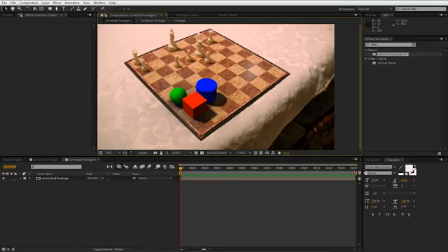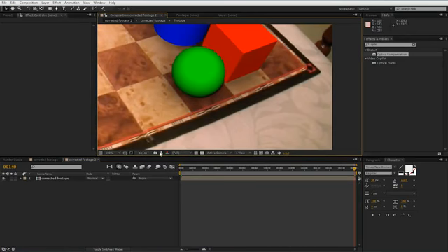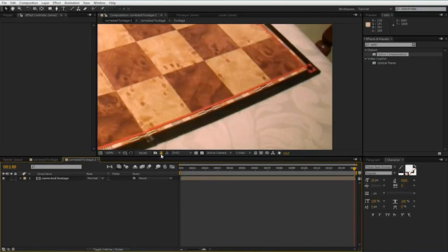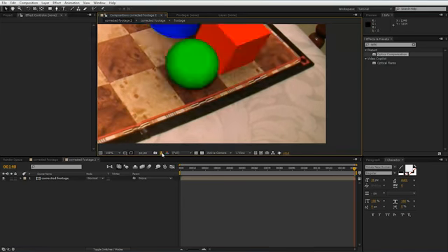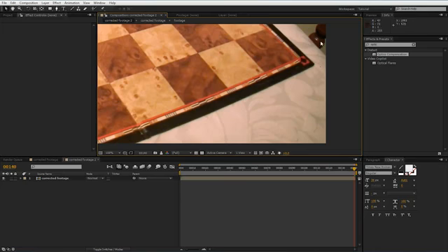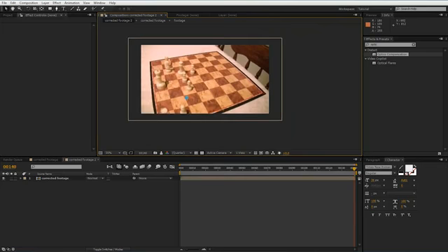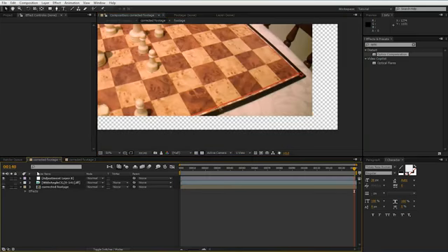It's looking really good. If we go to the last frame here, zoom in 100%, take a screenshot and turn the CG off, we can see that just slightly, I'm not sure if you can see this on the recording, it's actually getting some of the soft shadows of the final gather over here. And if we didn't increase the size of the footage by 20%, we actually wouldn't have rendered anything on the extreme edges. So it's really important to scale up your footage. And I'll just turn this back on.